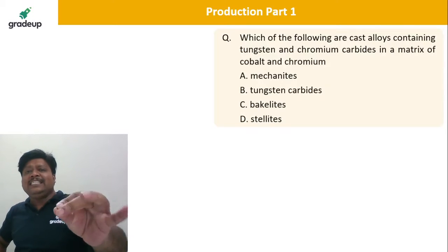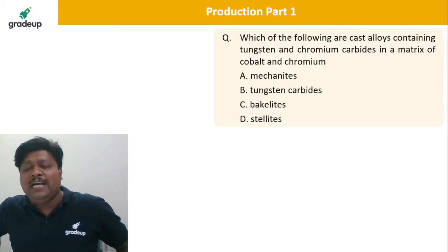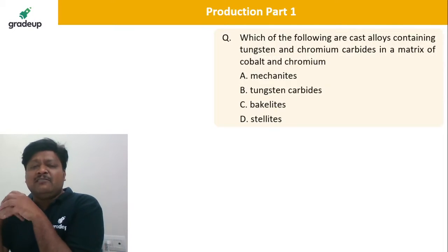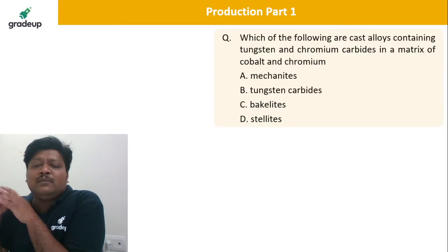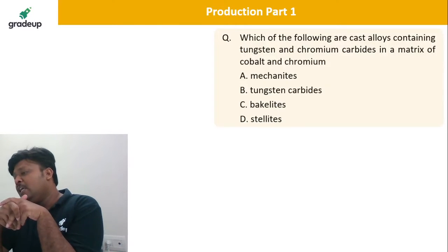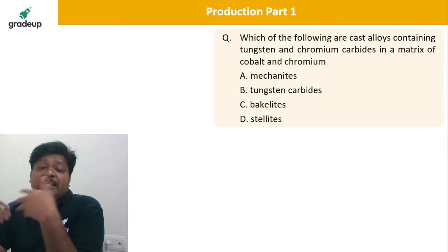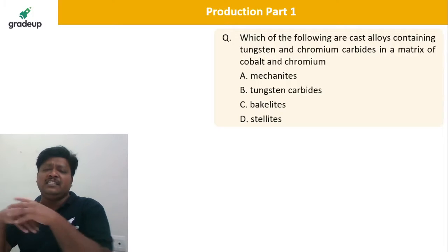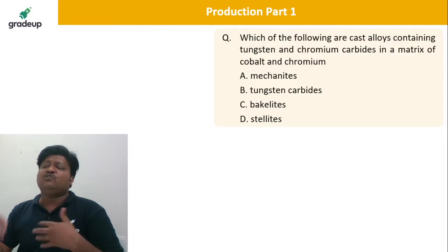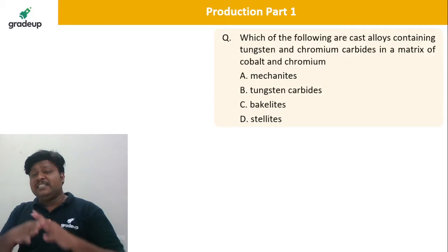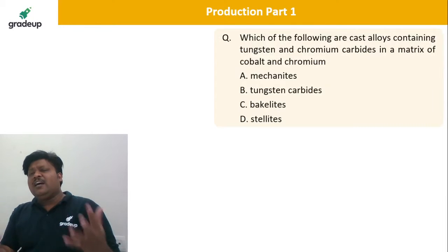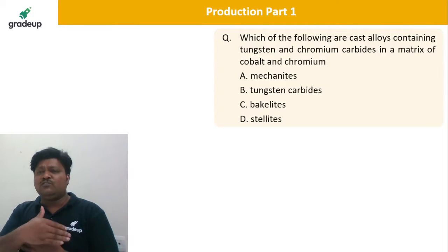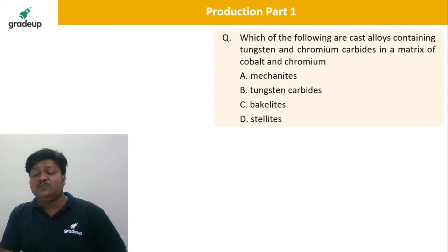Now see, there is HSS. Just now we talked about high speed steel. High speed steel generally has a limitation when used for machining of ferrous, because in the matrix of this HSS around 76% iron is there. That is the reason why it is not suitable for ferrous. The hot hardness temperature is around 650 degrees centigrade for high speed steel.